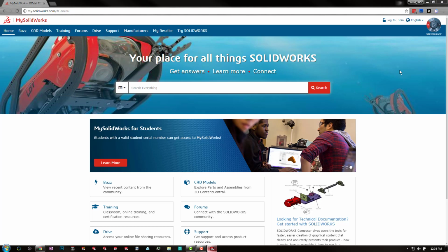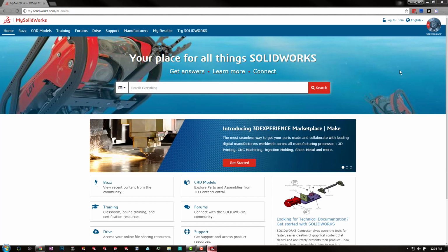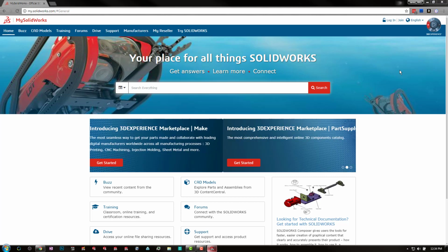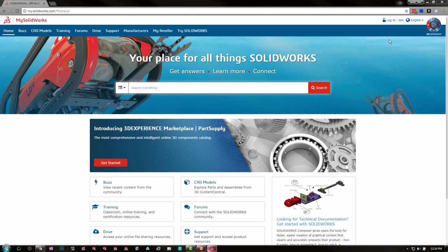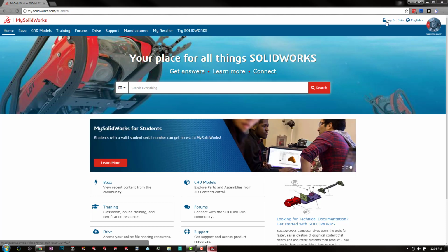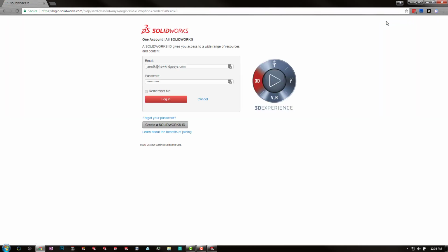This video covers the process of how to set up your MySolidWorks.com admin portal so that users can be set up for SOLIDWORKS online licensing. In order to begin, first create a login at MySolidWorks.com, or if you already have one, it should correspond to your customer portal account that has been set up at SolidWorks.com.